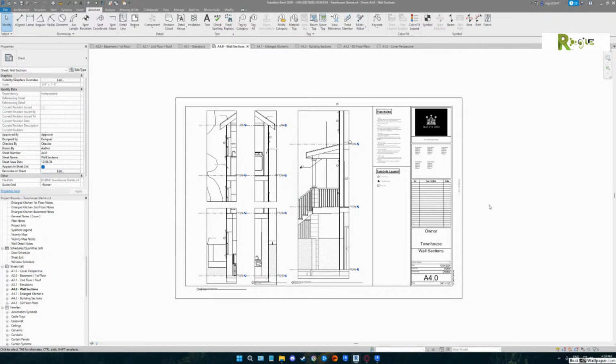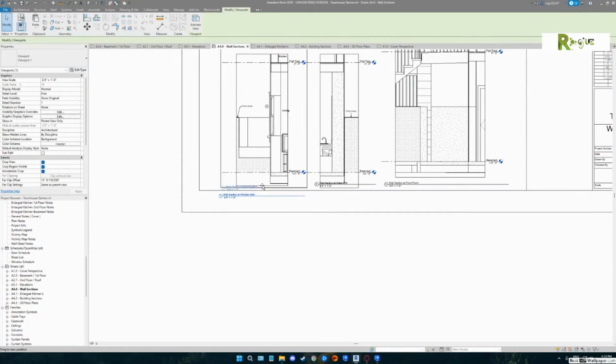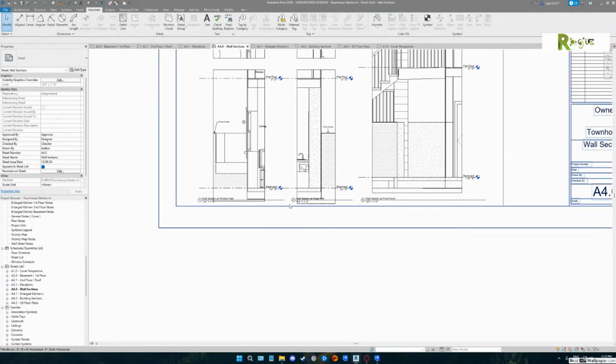I know you wanted to clean it off by taking off those titles. Clean those titles up. They should all line up with each other. First, the level line should line up, then the title bars should line up, and you can get them to line up independently. One we pick the view, the other we pick the title bar. So like in that first view, you should be able to grab that title bar right there and drag and snap. You got it. I just gotta fix the views. A little more than that, but yes.